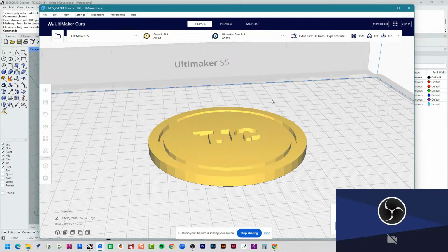Okay. So if you're doing something like this, an assignment just for my class, going fast or extra fast is totally fine. Just know that you're going to get less details, right? Let's say I 3D modeled myself in Rhino and I was 3D printing it. The thicker the layer height is, the more coarse I'm going to come out. The finer that line is, the more details you're going to see. You know, the curve of my jawline, the earlobes. But if you do it really extra fast, you're just going to get this big blocky 6 foot tall person. All right, so that's slicing.